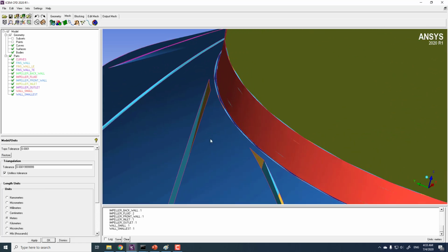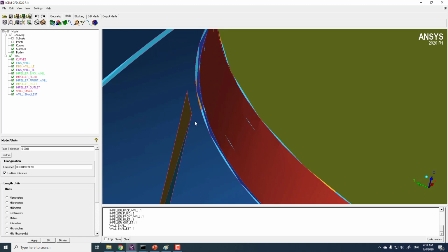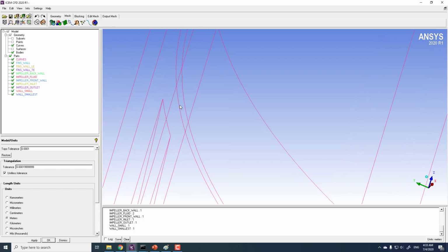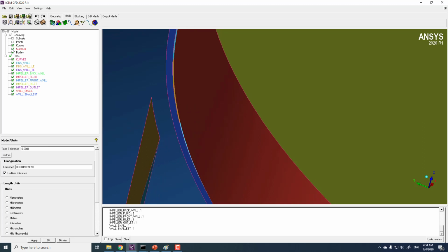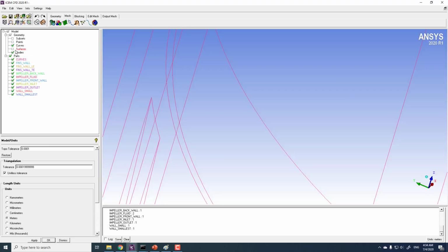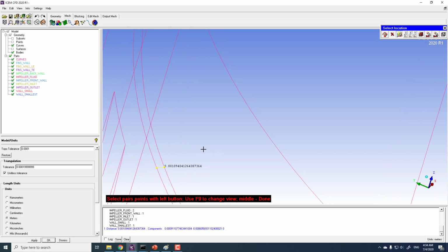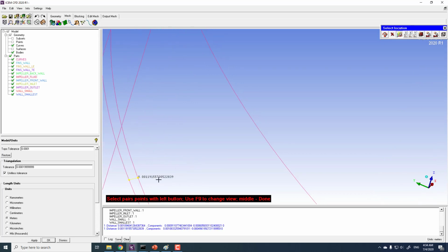And second thing, from here you can check the size of this tolerance is very simple. Now you can see that the minimum size of any surface, or smallest surface, is this one. And if I hide the surface from here and go to this measurement tool, roughly speaking, it's not a straight line, but roughly it's a straight line, you can see the size is 0.001.